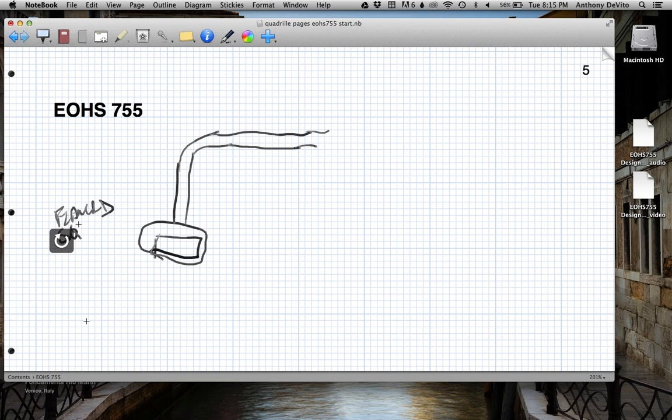Flanged square. Okay, so now, what quantity of air am I going to have to pull through this duct? How many cubic feet per minute? Well, first I need to know what is it I'm trying to do. What am I protecting the worker from? If you go to chart number 9, I think it is, which should be right behind your hood charts. There's different materials, different particle sizes: grain, wood dust, sander dust, silica dust, and so on. Silica is very high, a lot of feet per minute that you need. A lot of the transport velocity is very high.